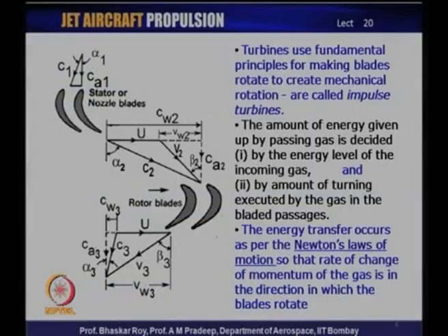Let us go back to the diagram quickly. The flow is now coming into the rotor. It has already executed a large acceleration. Flow has come out with C2 and it has a large velocity V2, which as you will see is much larger than C1. And with this fairly large velocity, it is coming into the rotor. Now, of course, normally you would see V2 would be a little lesser than C2, which means that V2 is now, in terms of actual value, lower than C2, with which it is now going into the rotor.